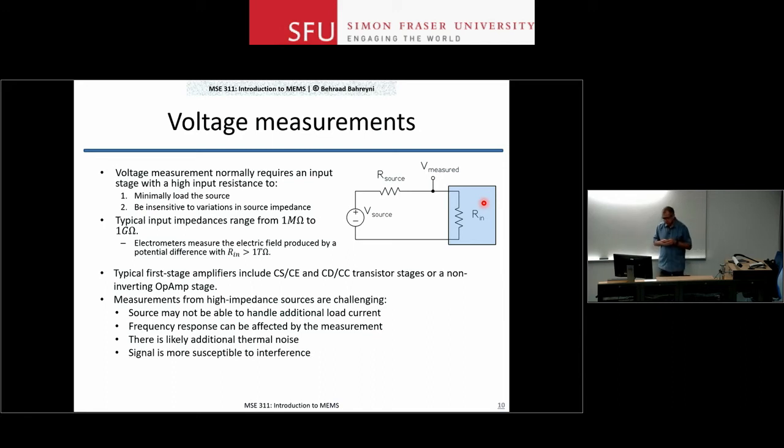And if you have a high impedance node, that high impedance node is more susceptible to interference. Basically, if there is a signal in the environment, it could be the 60 hertz or it could be anything else in the environment. If this is a high impedance node, meaning that once you put a charge here, it takes a long time for that charge to go away, and the impedance to everywhere else around this node is high, well, an interfering source here will be capacitively coupled to here.